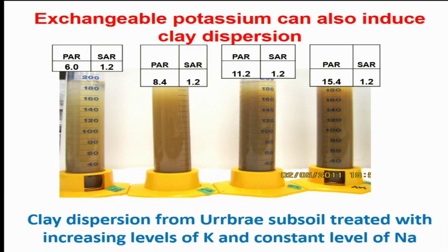When we worked on a project funded by GWRDC, Grape and Wine Research and Development Corporation, to look at the effect of winery wastewater irrigation, we came across that winery wastewater contains a lot of potassium. In order to avoid sodium in the wastewater, they started using potassium hydroxide for cleaning the winery equipment. Because of that, the potassium concentration started to increase, and in some of the wineries, they found that the soils are affected.